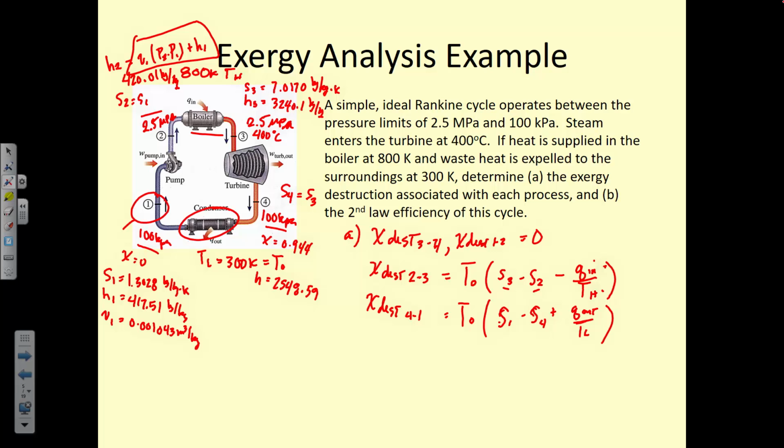What did you say again about using the pump work added to H1 to find H2? So you don't have to use the work of the pump when it's a high enough pressure is what you're saying? It's for the tables. We have tables in our book, table A7, for a compressed liquid table, right? So it starts at 5 megapascals.